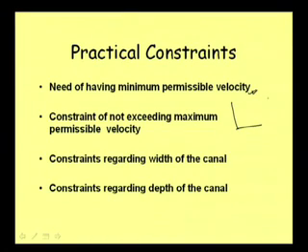And as we know, say this is our canal, and from the upstream a lot of sediments are coming, and then sediments are settling down because the flow velocity is less. For water, its sediment carrying capacity depends on the flow velocity. Well, if its velocity is high, it can carry more sediment.